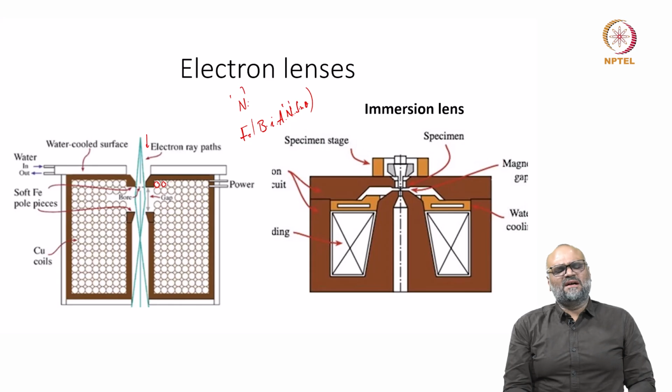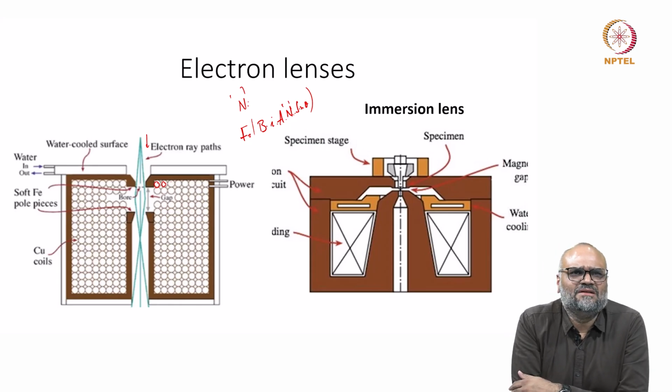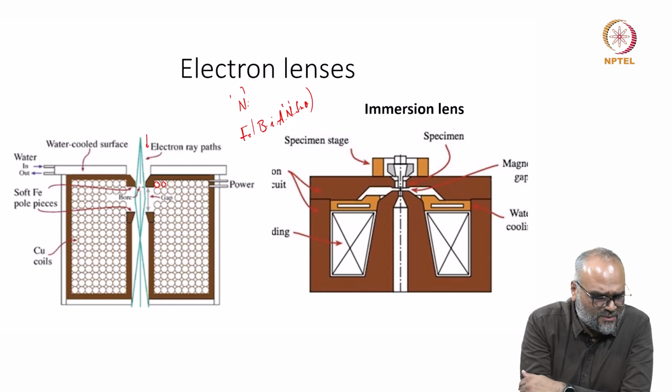You do not want to cause any kind of thermal expansion, which can in turn lead to some kind of instability. When you want to achieve resolutions as high as less than 1 angstrom, bear in mind, if the lens is maintained at 18 or 17 degrees centigrade or at the ambient conditions of the room temperature, I really need to circulate this chilled water.